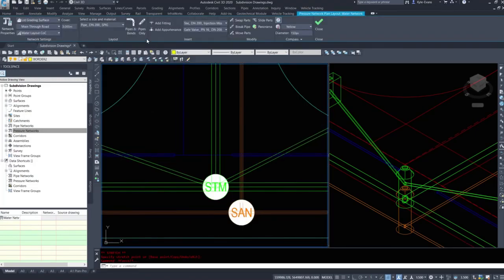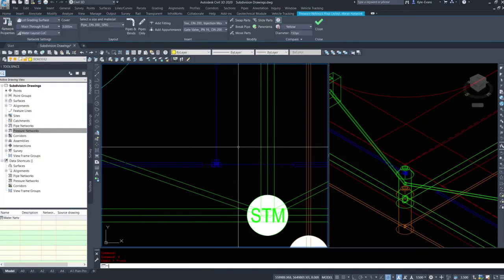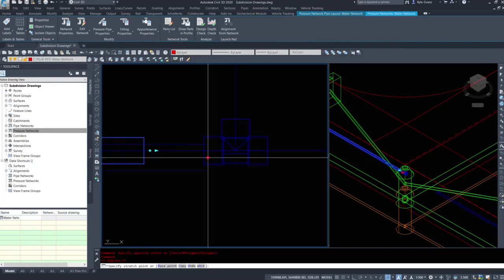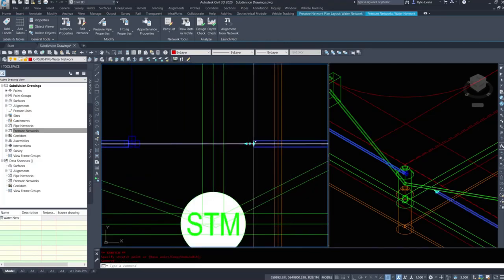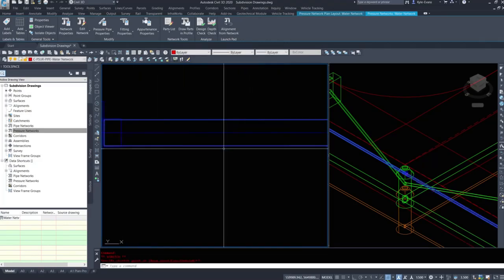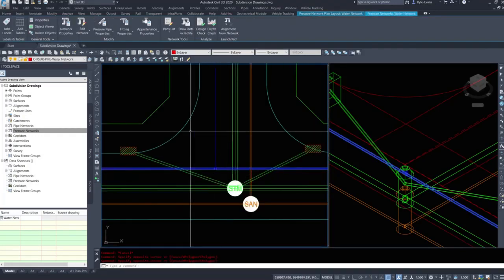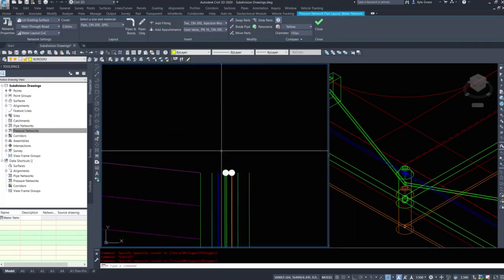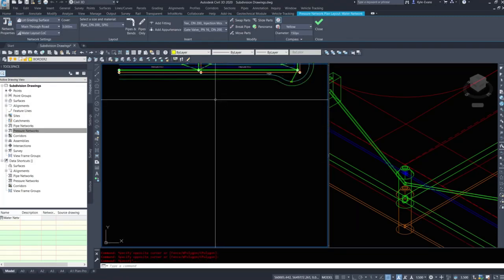However, I can simply go T, add a fitting. I want it right there. Get rid of the labels. And it's as simple as selecting the grip, looking for the little circle with the 4 crosshairs glyph, and attaching it to your T. And if the grips on your pipes go away, that is how you can confirm that it is attached to the fitting itself. We have no fitting here. It'd be tied into existing. Up here, there'd be a cap, or we'd continue on into the more of a subdivision design.